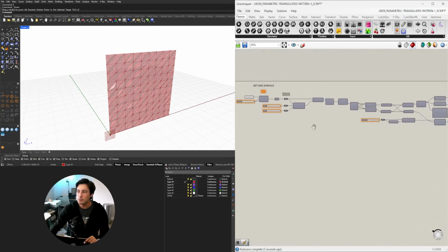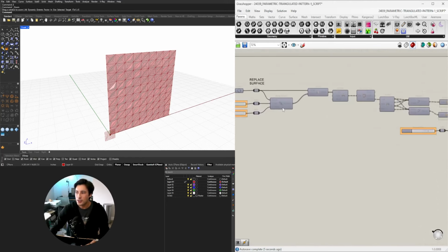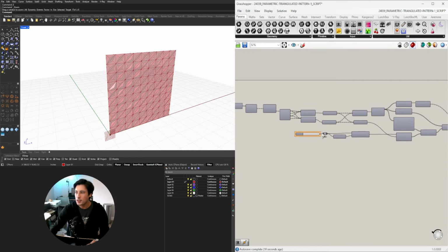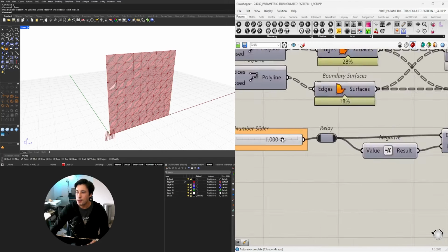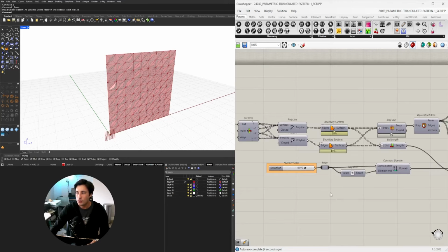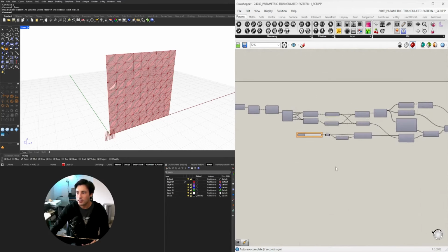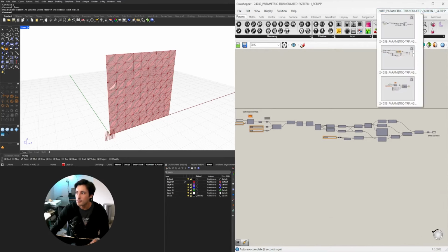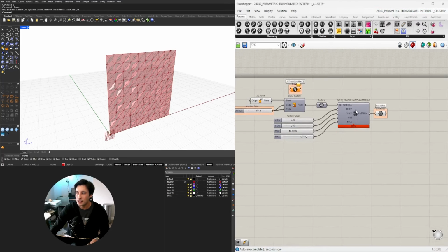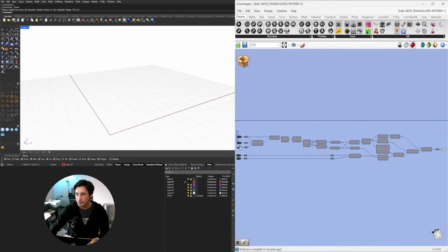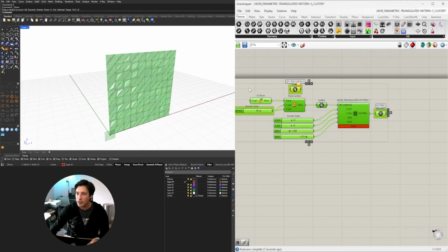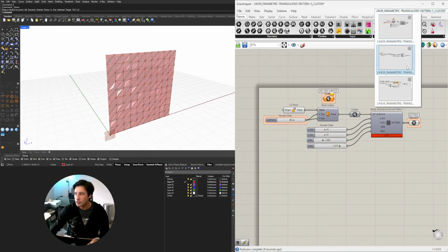Now, this is a simple exercise, so you understand how to take isotrim subdivision and then turn it into this random triangulated pattern that has a minimum and maximum to kind of expand that pattern. So what you'll see is the beginning part, which is creating this. Then you'll see the cluster, which is nothing more than the entire script organized using the inputs and the outputs here. So with this simplified version, then we went ahead and created this exercise.